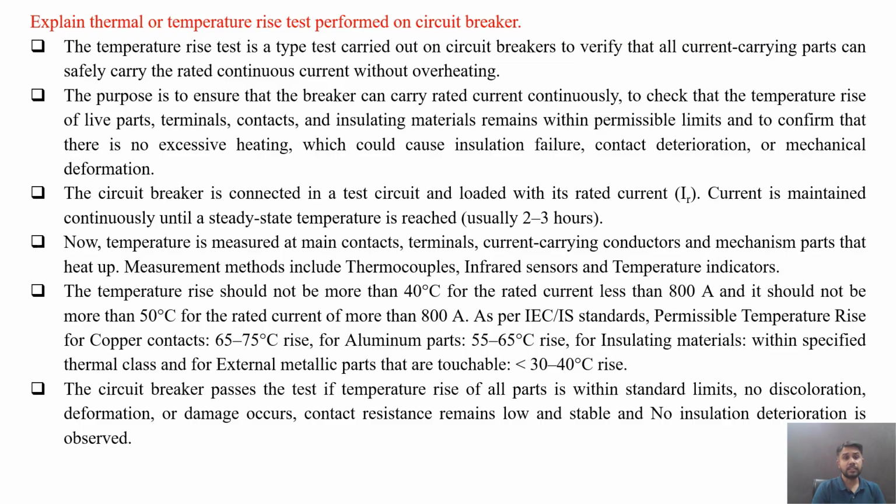The purpose is to ensure that the breaker can carry rated current continuously, to check that the temperature rise of live parts, terminals, contacts and insulating materials remains within the permissible limits, and to confirm that there is no excessive overheating which could cause insulation failure, contact deterioration or mechanical deformation.